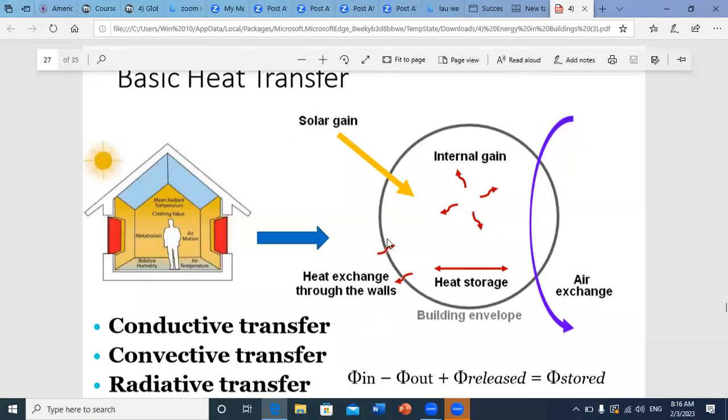We should know what is the heat exchange through the wall, so we can study heat exchange by conduction within the envelope, because we'll see together that mainly in a solid, the main mode of heat transfer will be by conduction, that we'll discuss in a while. And at the inner and outer sides, the main mode can be convection, because you have a fluid moving over a surface.